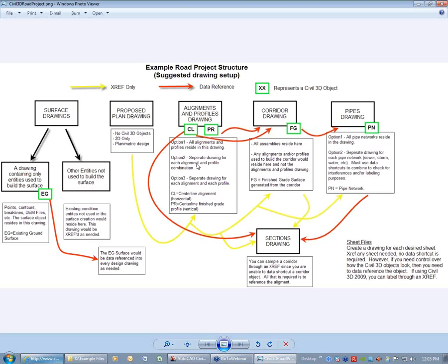As you've been using Civil 3D, you can understand that as the drawing gets larger and more entities are inside it, it tends to be a lot slower and also tends to crash more. Of course, Civil 3D crashes every now and then, but to minimize that, you want to separate out your Civil 3D objects as much as possible. The big reasons are, one, you can share work between the project, and two, you keep it small. Being much smaller, your computer doesn't use so many resources, and it stays open and doesn't crash as much.